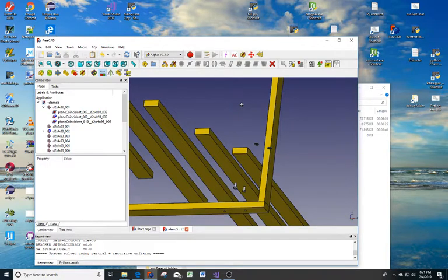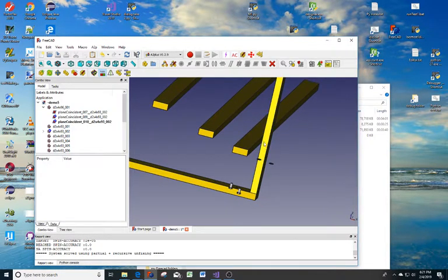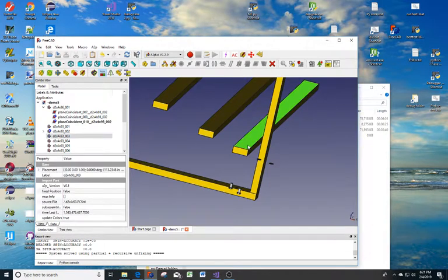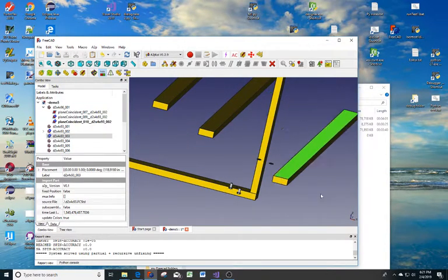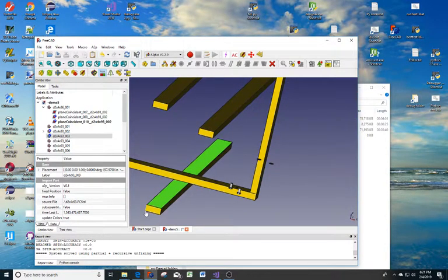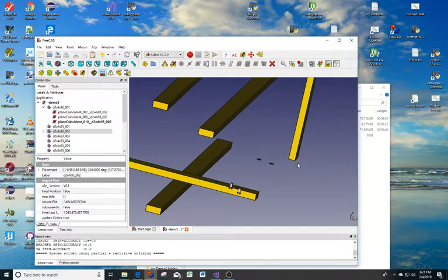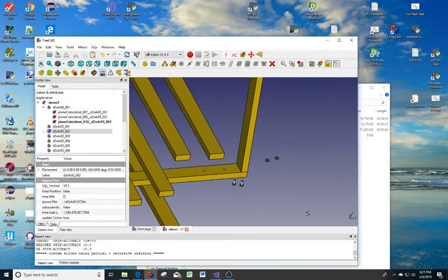You can move these pieces around if you want to. I'm going to move this board and this board out of place. So I select this one. I come up here to move selected part, and I move it out of place. I can select this one, move the part. But the difference between those is that this one has constraints. So when we run this solve button, it will put this board back into place. Here goes the button, and you can see how the constraints work there.